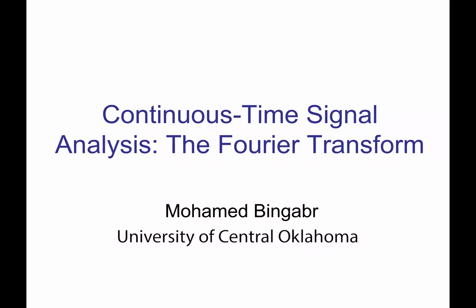Hello everyone. Today we're going to talk about continuous time signal analysis using the Fourier transform. Just to give you the big picture, if you have a continuous signal that looks like this, and let's call this signal x of t, and you want to know the Fourier transform, or the frequency content of this signal, and this signal is not periodic, so it may have infinitely many possible frequency components, like 0.111 hertz, 0.00001 hertz, and 1000 hertz. So we cannot use the Fourier series analysis in this case.